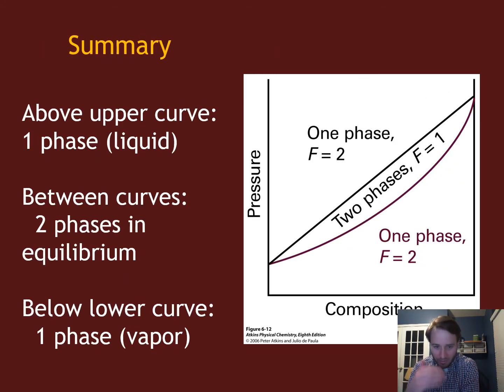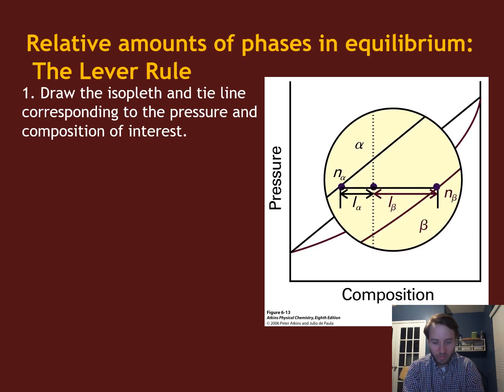So again, a summary of this two-component phase diagram: we have liquid and vapor phases that exist here, and then we have a region where the two phases are in equilibrium, but it's no longer just a line. It's now this chunk, this surface, that has two phases in equilibrium. Otherwise, it's very similar to things we've talked about with single component phase diagrams. And so one quick note